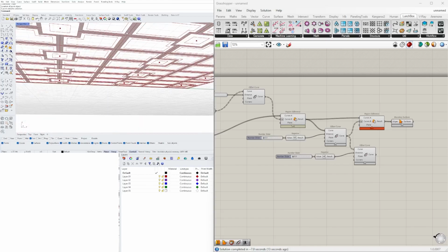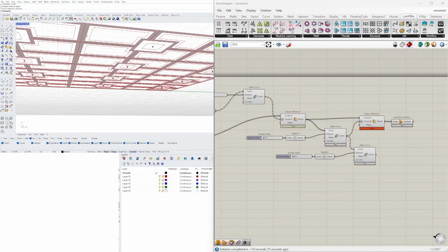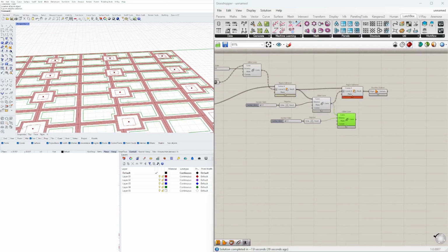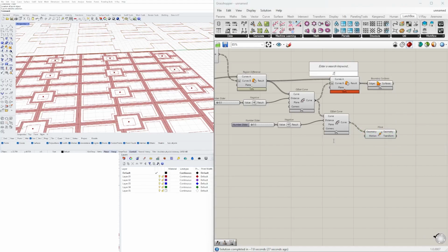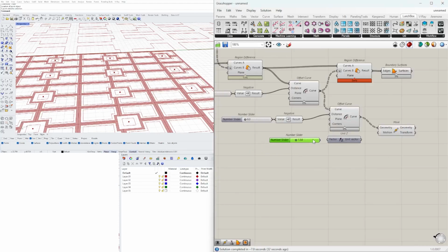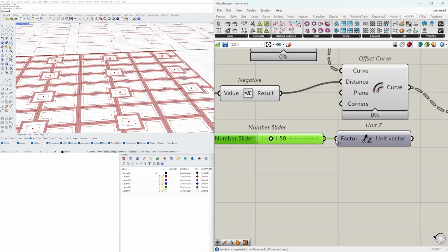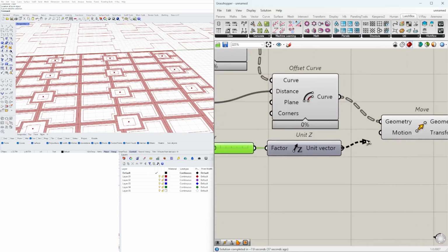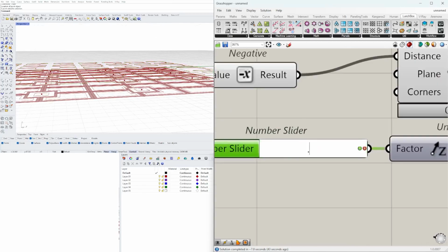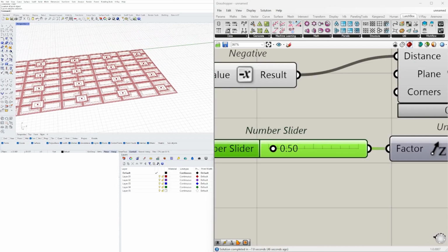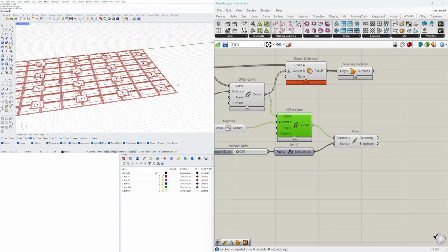So this from the bottom is going to look like, okay, this is concrete. And now we're going to start tapering up. So this is where we take this and we move this up. So we'll go to move. And depending on how thick your slab is, in the Z direction, we can just say 1.50, so we have a little bit more control with the decimal point. Now we're at 0.5 here. So we have moved this up.